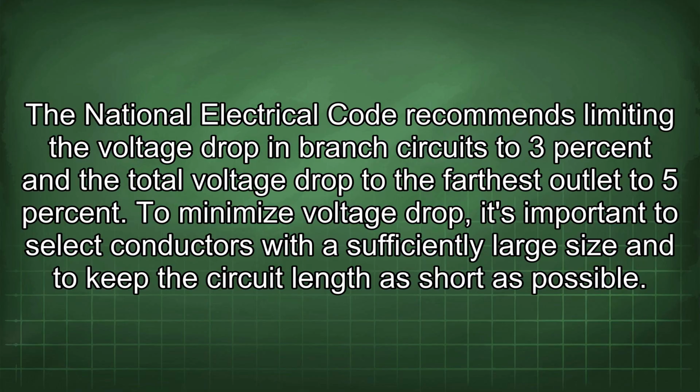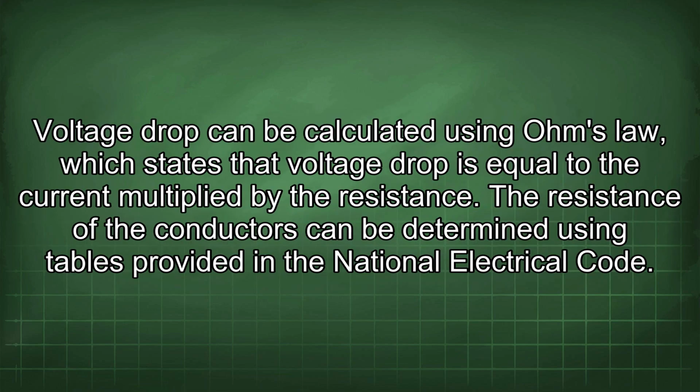To minimize voltage drop, it's important to select conductors with a sufficiently large size and to keep the circuit length as short as possible. Voltage drop can be calculated using Ohm's law, which states that voltage drop is equal to the current multiplied by the resistance.